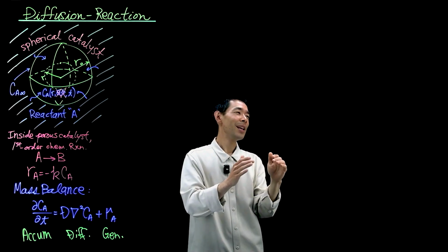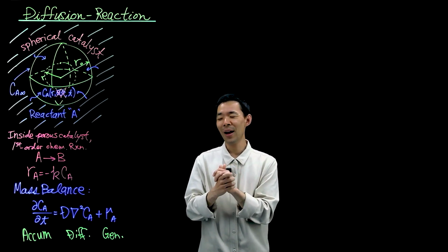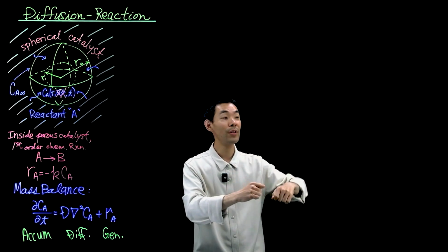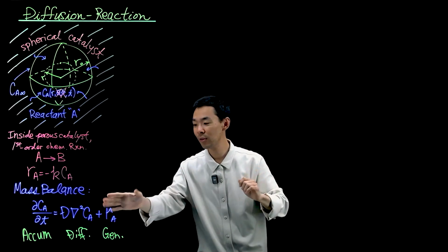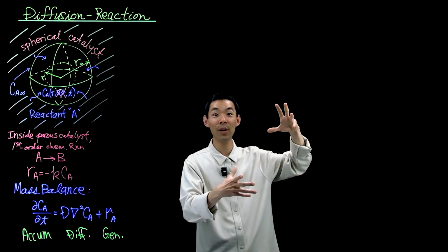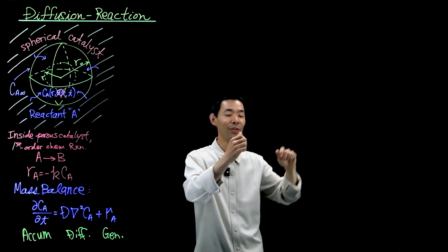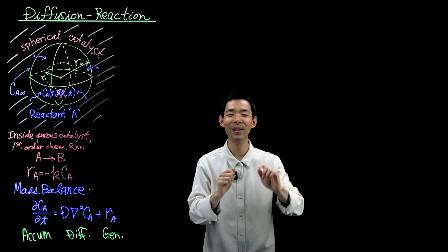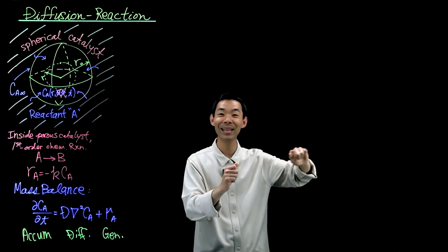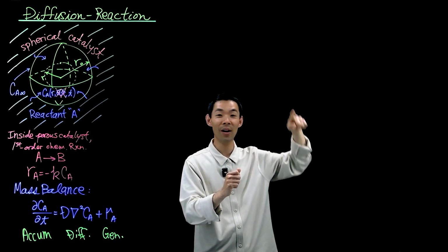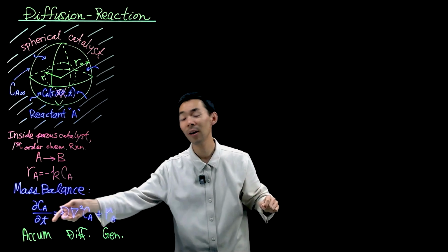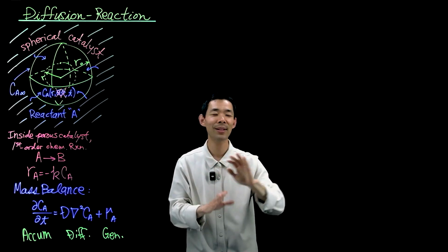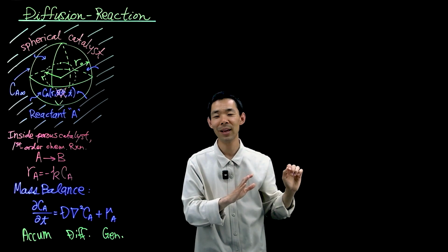Of course, if you're really a chemical engineer, you have to think about disturbances and noise, and you have to think about feedback and control. What if the temperature fluctuates outside? What if the exothermic reaction causes the temperature to run away? Then you have to add a heat jacket, you have to apply a controller. Okay, in those cases, sure, you need a transient term because feedback is automatically going to be dynamic, time varying. Noise is often time varying, and therefore you'd have to account for this accumulation term. But let's do the ideal case. Ideal case, steady state operation, no noise on the outside.